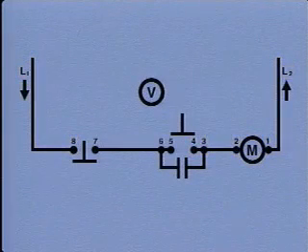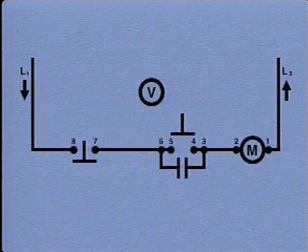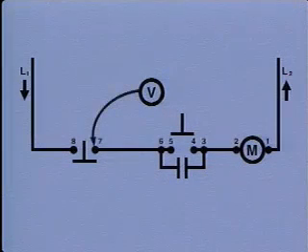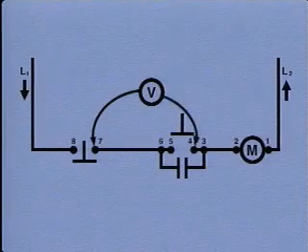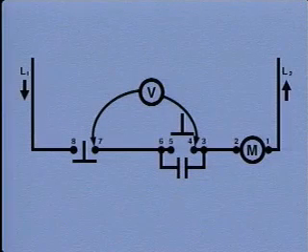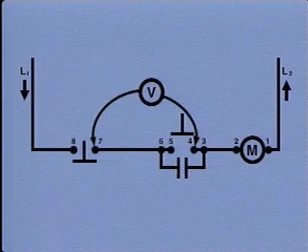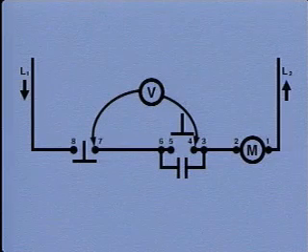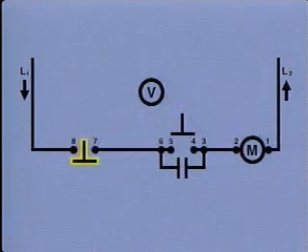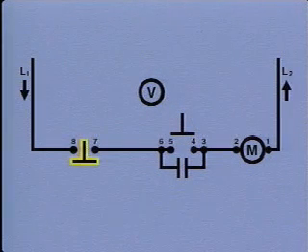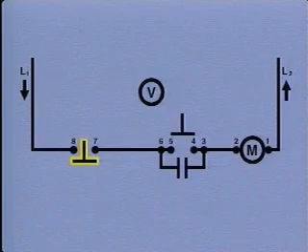This means that the open must exist somewhere between connection point 8 and connection point 4. So the final test is made from connection point 7 on the other side of the stop button to connection point 4. The voltage tester reading for this test is 0, which means that voltage is unable to reach connection point 7. This reading indicates that the stop button is malfunctioning and is, in effect, open. The problem is now isolated and it can be corrected.